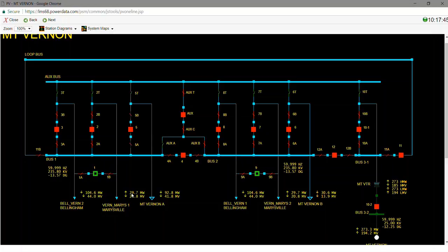Now there are a specific set of tolerances that must be met in order to close a breaker regarding the voltage, frequency, and angle on either side of it. When you're tying islands together, for example, and we'll get into that, your rotating angle has to be within a specific tolerance, but just for normal operations, the voltage tolerance for closing a breaker is 30%, the frequency tolerance is 0.1 hertz, and the standing angle is 40 degrees. Those are global set points across the entire system, so no one will be any different from another.